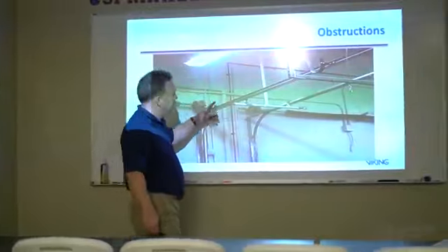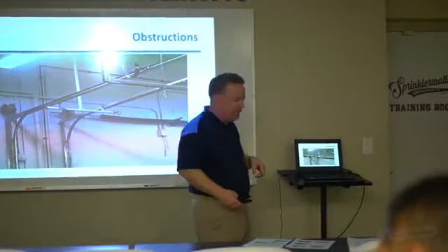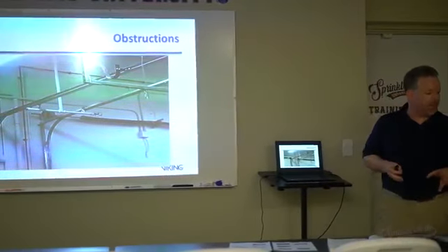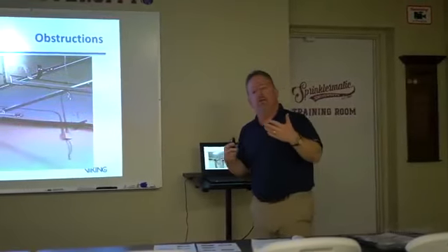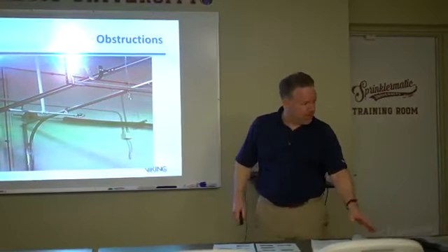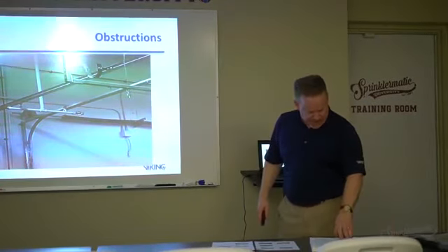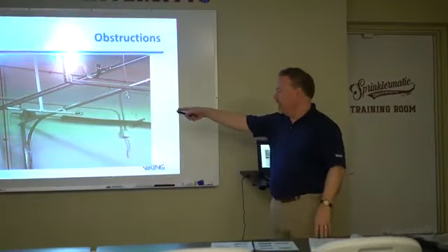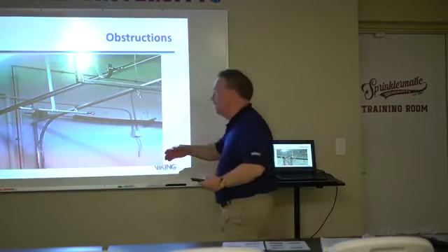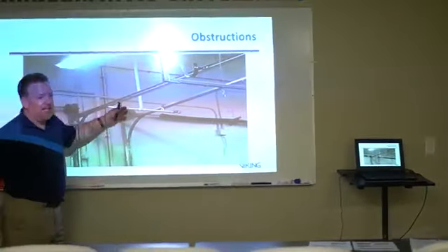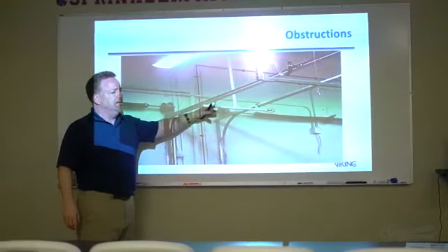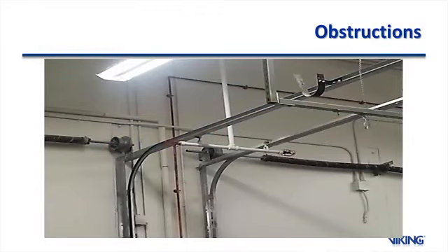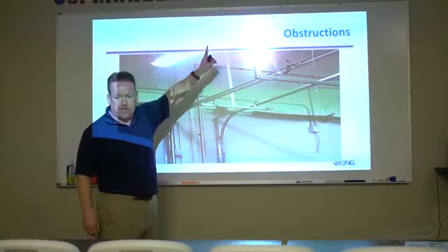Now in some cases, and this is one of those things where I said earlier, remember I read out specifically the general rules about sidewall sprinklers. And we said you can put them under what? We can put them under flat, smooth ceilings, right? And in light and ordinary hazard occupancies. And then it is to protect areas below overhead doors. Specifically right here. So these look like they're really far down from the ceiling line, and that's true, they are. But once I open these overhead doors, what's obstructed? All my ceiling sprinklers are now obstructed from above.